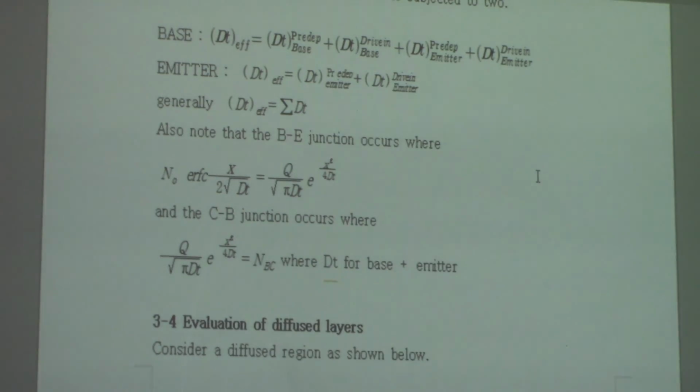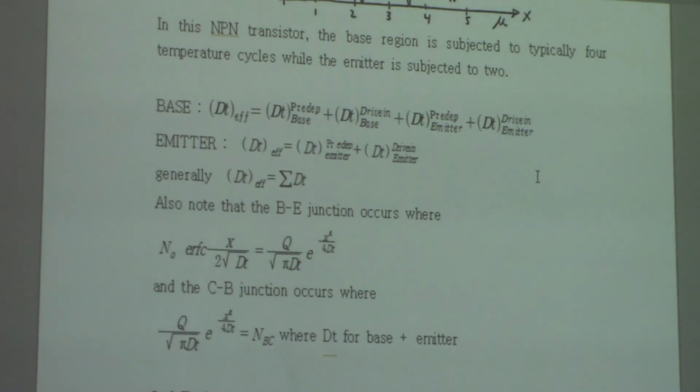Okay, and for the diffusion profiles, every thermal cycle has to be added together to determine the final diffusion length. So all the heat treatment should be added